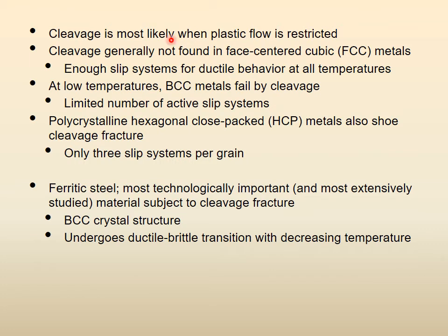Cleavage is most likely when plastic flow is restricted. The material is trying to deform in the plastic region. If it is restricted, if it is stopped, then you keep on stopping, and suddenly it breaks completely through. Cleavage is generally not found in face-centered cubic metals, right?